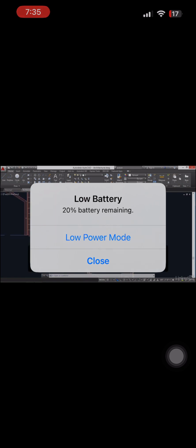To do that, I will actually move the chair down here, rotate it, and then move it back. I'll move this chair, Enter, from a base point, which is maybe right here at the midpoint of the backrest. So to get that, I'm going to have to hold down the Shift key and right-click to open up the Object Snap menu. Then I'll select Midpoint and click right here.